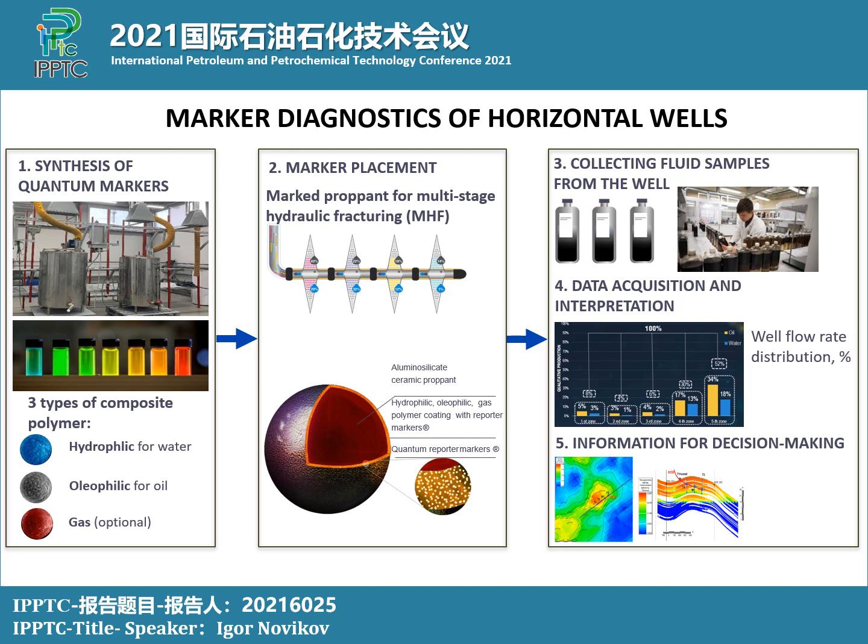And the third step, we collect the samples at the surface once the well is opened and the fluid is coming to the surface. We take these samples and send them to the laboratory. They analyze it and give us a result. The result says how much inflow from each port and what kind of fluid from each port comes. And this data is presented in percentage, so this is quantitative data. And the last step, this information might be used to make a decision of how to develop the oil field.